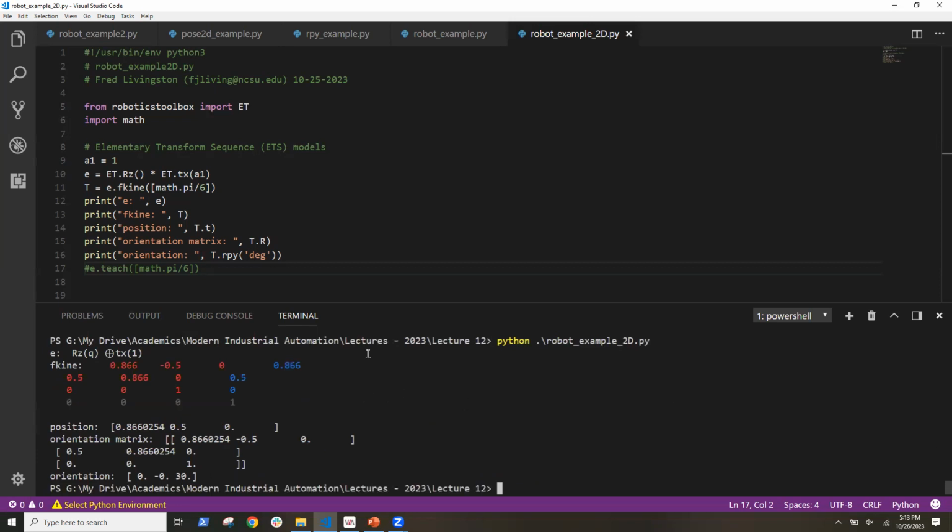Okay. And you can see it's the rotation Z, and I'm going forward, so it's a plus. And this is my 4x4 matrix. So the red is the rotation, and then this blue is the position, and the robot is at 30 degrees. Where is my robot end effector located? The XYZ position: 0.866, and then since it's a 3x3 example, 0, 0 in the Z direction.